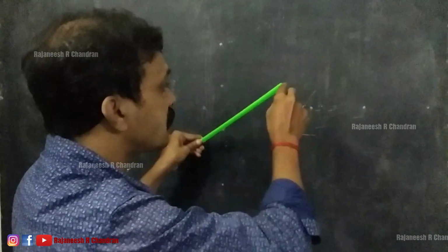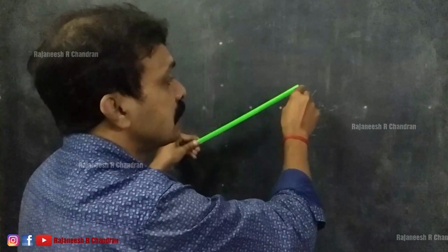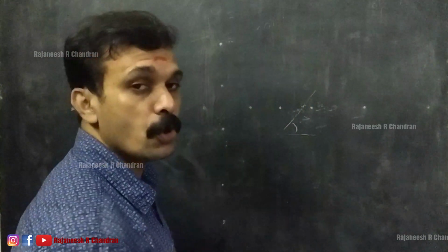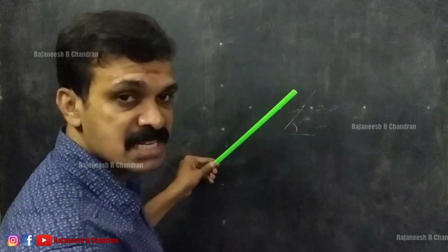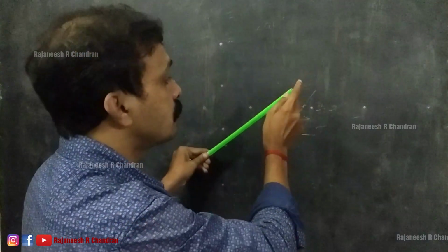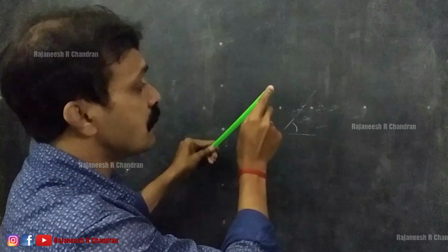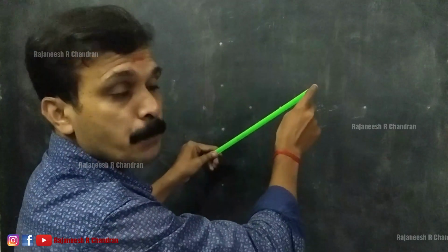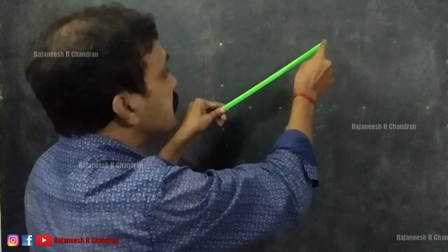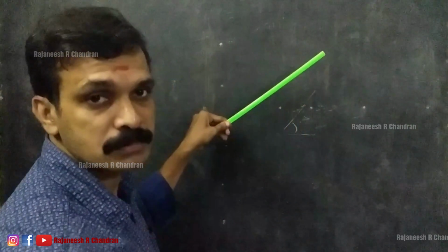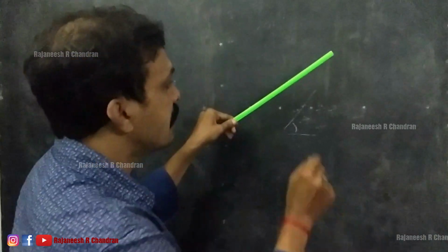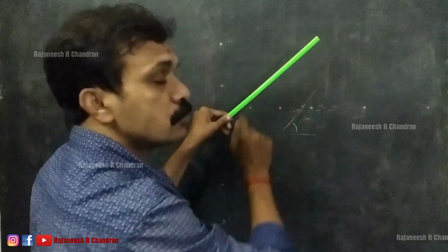That means this height will be the same while rotating the line. So keeping the elevation height, or the height of the front view of this point, constant and keeping this point fixed, we can rotate this line from any position and make this line parallel to VP. So you can see that now this line becomes parallel to VP.